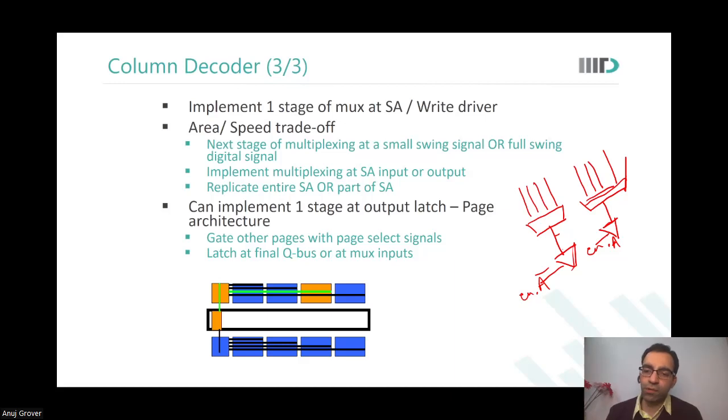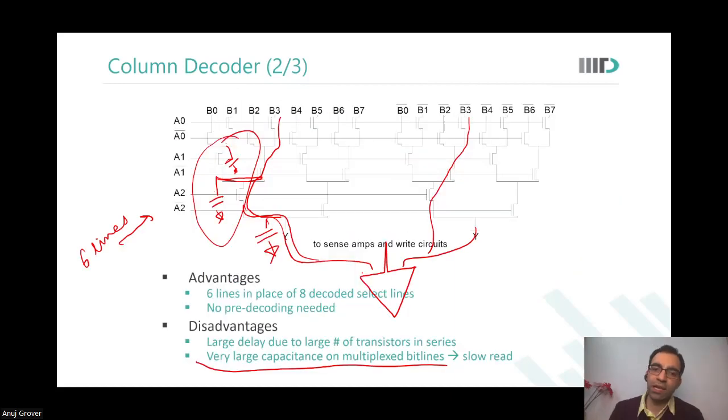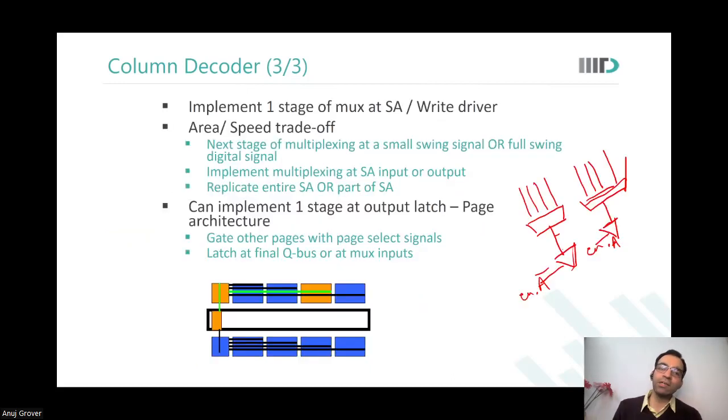So if it was a higher mux, in the previous slide we saw that if it is mux 8, there is a huge capacitance of 8 columns over here. Okay, got it. Yes. So by using this kind of a composite or hybrid mux, you could achieve better performance.